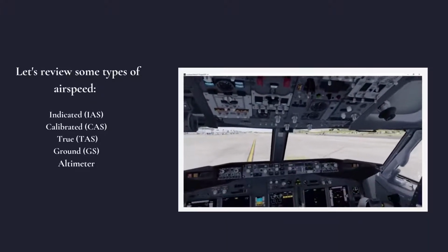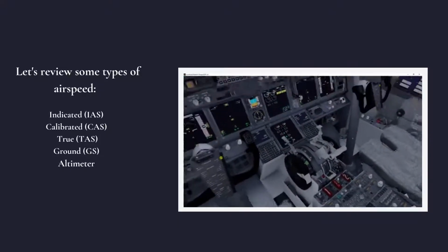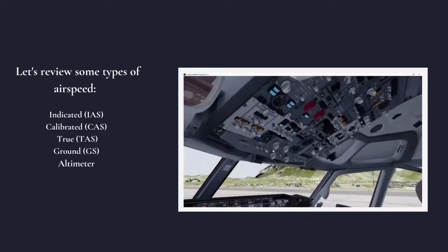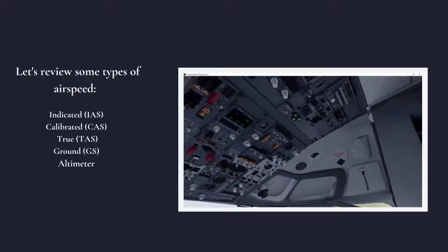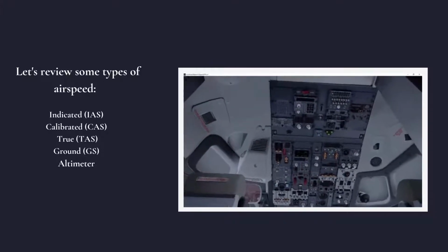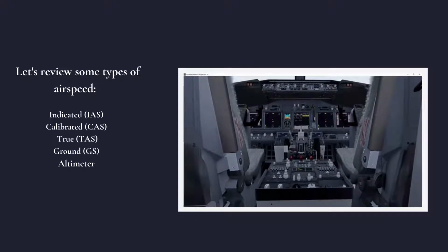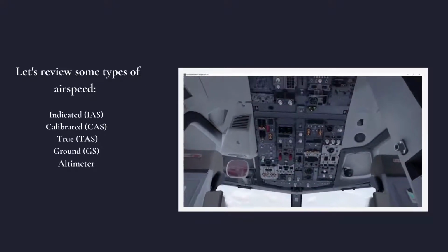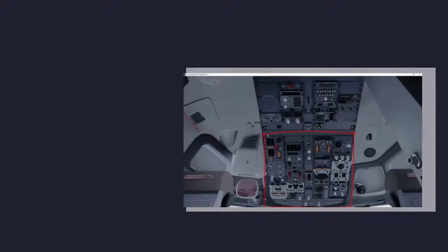Altimeter. The altimeter is an aneroid barometer that measures the atmospheric pressure at the level where we fly and presents an altitude indication. It uses static pressure for its operation. Remember that air becomes less dense as we ascend. The higher the altitude, the lower the pressure. This pressure difference at various levels causes the altimeter to indicate altitude changes. The cause of pressure changes directly affects the indication accuracy. The altimeter has a knob for adjusting the scale.